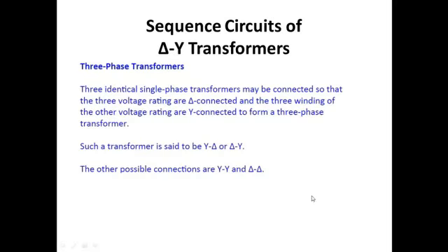Actually, in power systems we have a large number of three-phase transformers. And what are three-phase transformers? These are three identical single-phase transformers connected in delta and Y configuration, and based on this configuration we call them delta-Y or Y-delta configuration, or YY or delta-delta configuration.